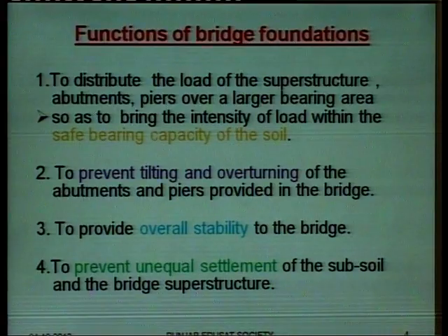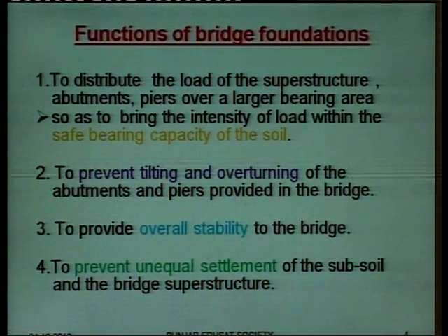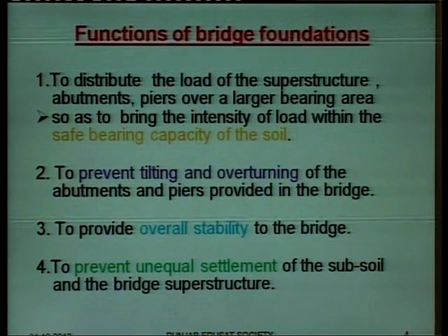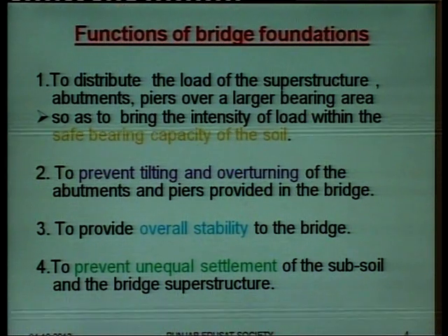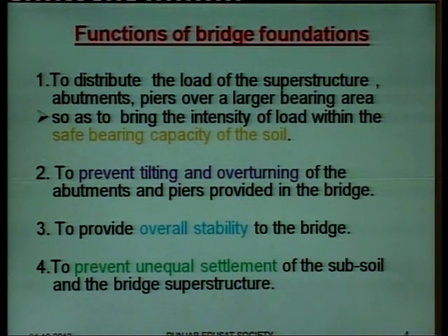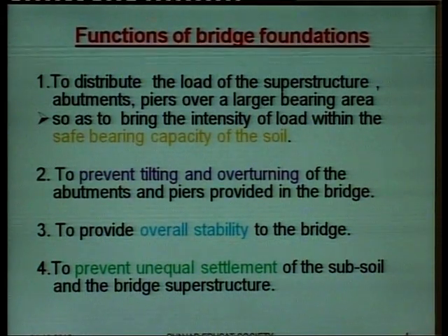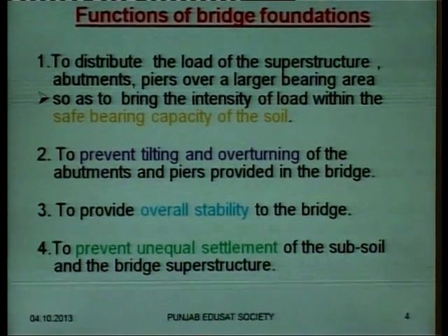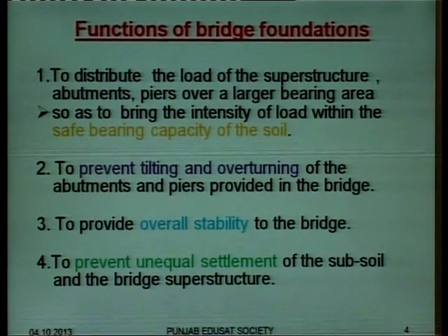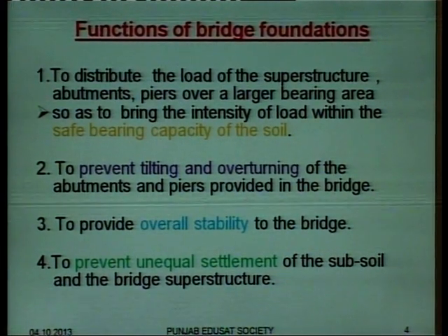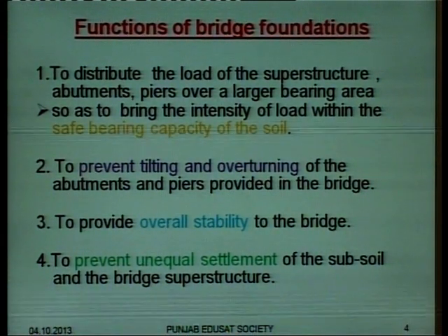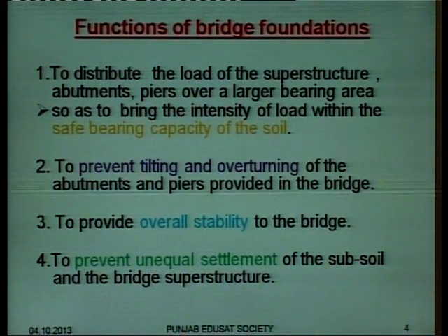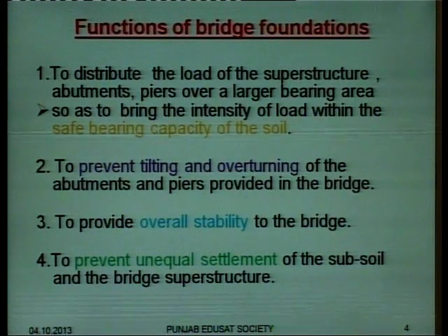Now, regarding the functions of these, the very first function of bridge foundations is to distribute the load of the superstructure, and of course the substructure part also, the abutments and piers, over a larger bearing area, so as to bring the intensity of load within the safe bearing capacity of the soil. As we all know, during the designing of a building or bridges, the bearing capacity of the soil plays a very important role.